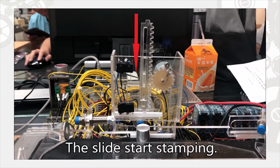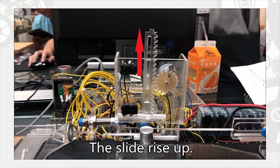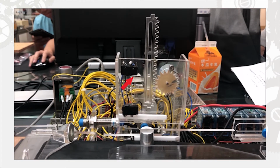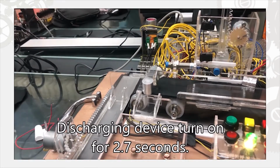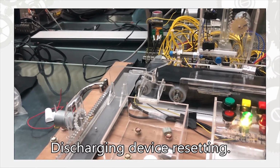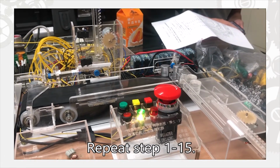The slide starts stamping. Lower limit switch induces. The slide rises up. Upper limit switch responds. The conveyor works for 5 seconds. Discharging device turns on for 2.7 seconds. Discharging device resets. Repeat steps 1 to 15.